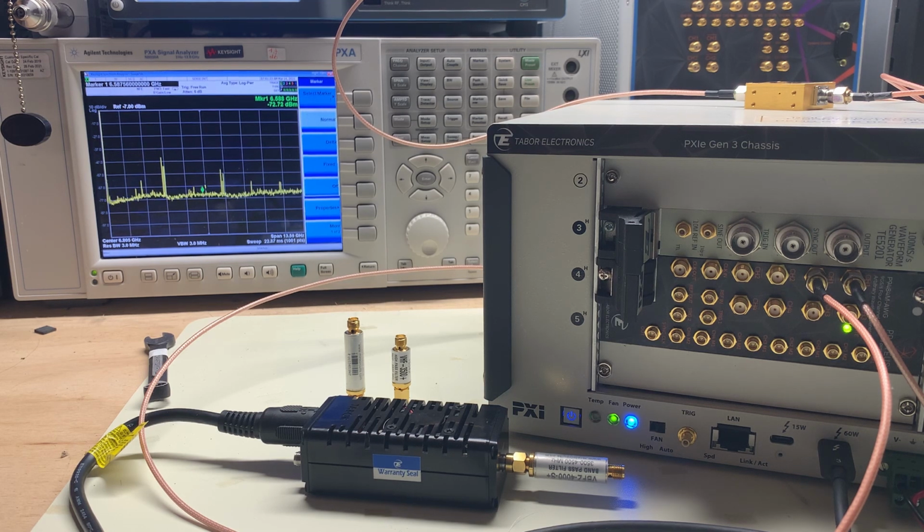We could use the pulse as is and just filter around it. So if I tune the spectrum analyzer, you can see the pulses there at 4.0749 gigahertz. The only issue is that, if you remember when we showed the full span, and I go back to the full span here, we have a sin x over x roll off, so you can't see it as well now the interpolation is on, and we have quite a fall in amplitude as we go along.